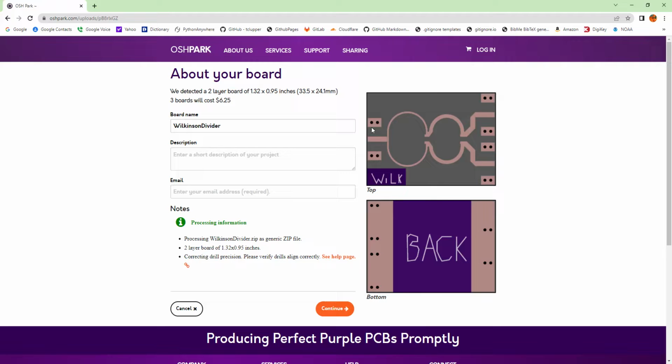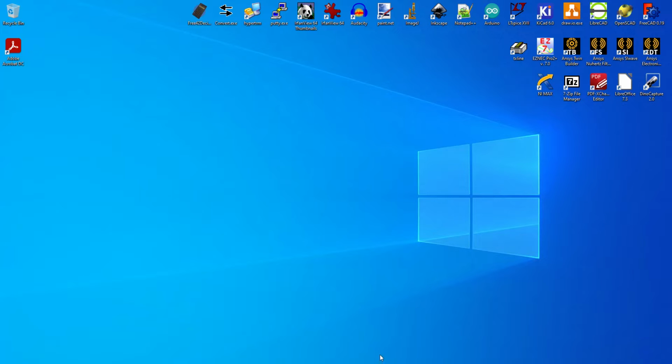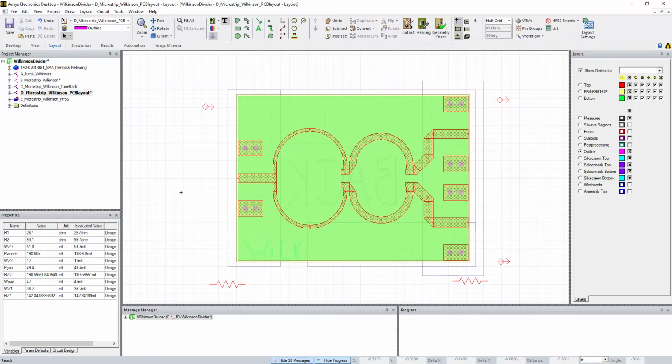So the top board should look like this, where the lower left-hand corner has a little bit of the solder mask. Their solder mask is purple. And then here's my top silk, and here's all the metal. And then my bottom would look like this. This will be gold. Here's the solder mask, like I said, and see how the back is now shown like I'm looking at the bottom from underneath. This is looking at the top from top. So this tells me, it's like a design rule check that, yeah, these were done correctly. And so that's kind of a real quick overview of what you're going to be doing.